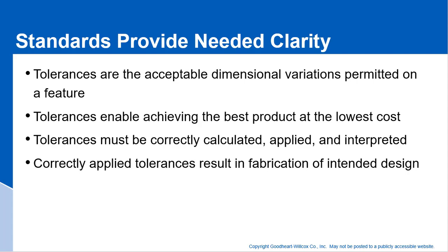what we do in mechanical parts and assemblies nowadays is all parts are interchangeable. We make assemblies with interchangeable parts. So we define the parts on drawings and we send those drawings out and manufacture the parts to the drawing, knowing that if we've done our work properly in terms of defining the tolerances and defining all the parts properly, once we get this basket of parts together, we will put them together and they will function as intended at the next level assembly.